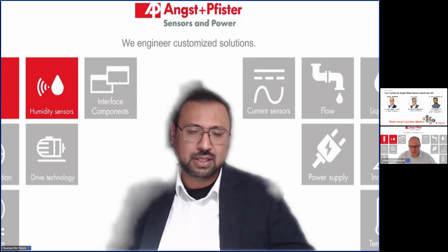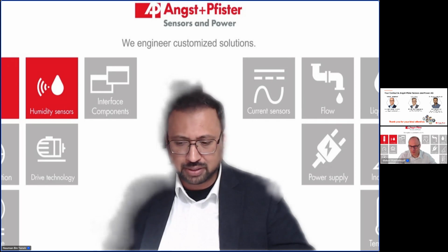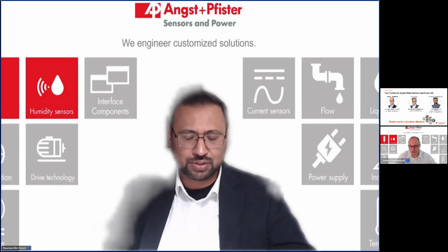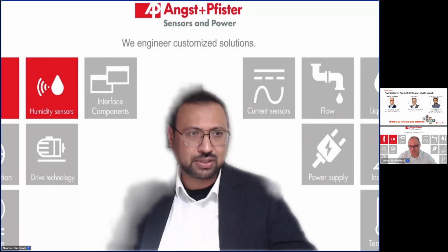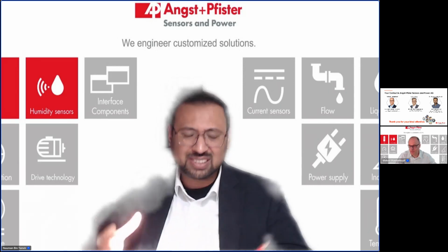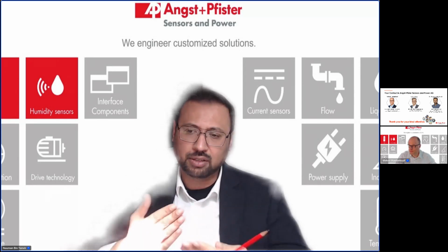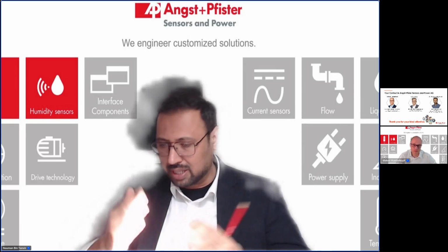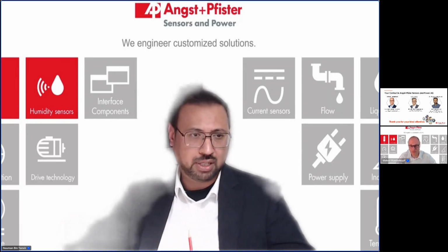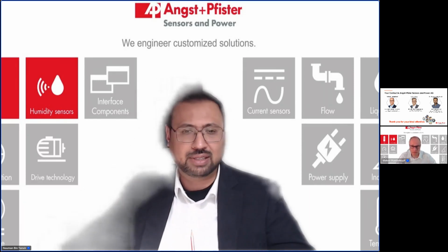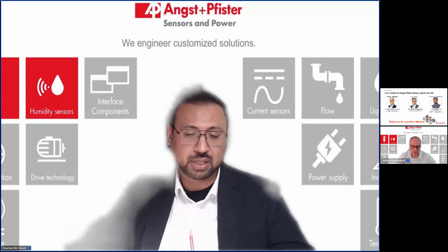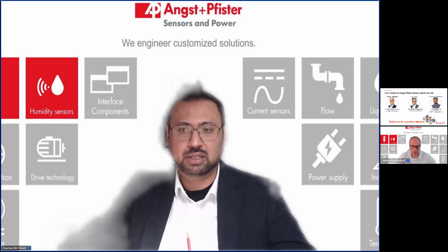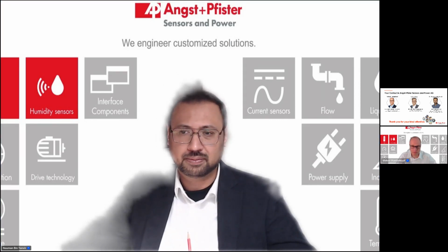I mentioned it also. The measurement cell is heated at around 55 degrees centigrade. One of the reasons is to get rid of certain temperature dependencies on this principle. This is an optomechanical principle, and the force which is being applied, you need to detect it. Ambient temperature and ambient pressure will have an influence, and that is why our measurement cell is heated at 55 degrees centigrade, in order to protect the sensing element against these deviations.